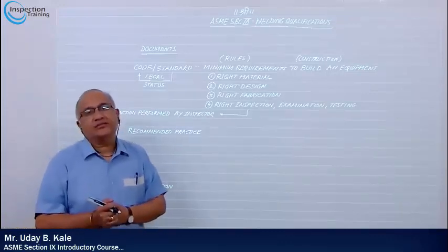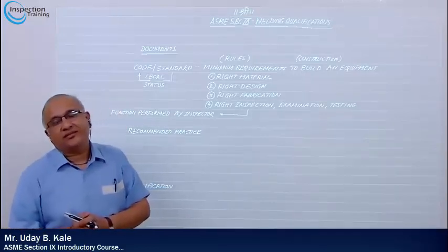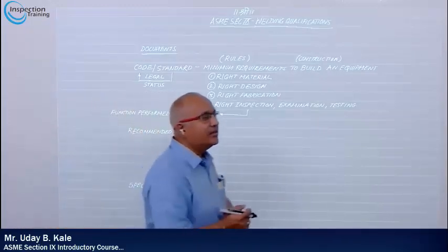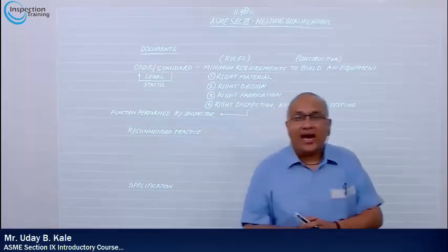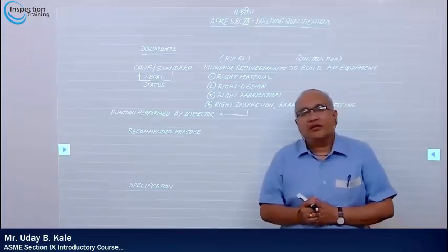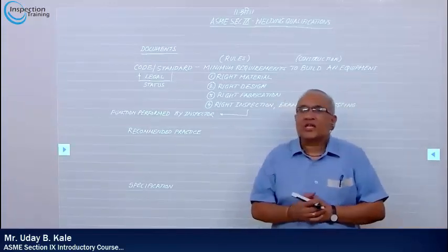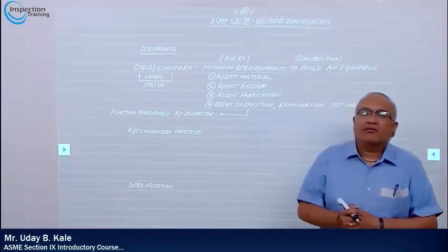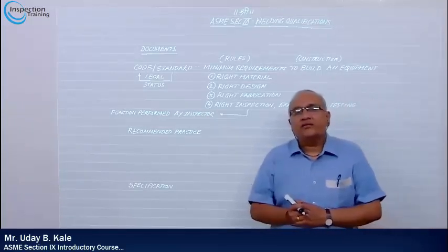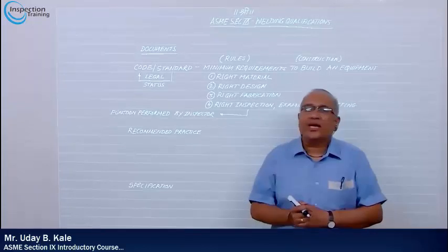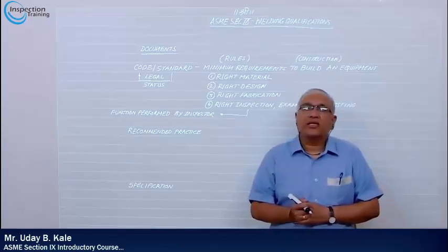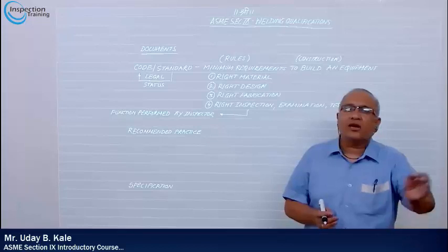As simple as that. If you really follow the inspection and test plan, then you will find there are many witness points, many review points, many hold points. One must understand the activity and its relation to inspection. When the project starts, there will be review points. Reviewing qualifications of welding personnel or non-destructive examination personnel is a function of the inspector, and it is called inspection.